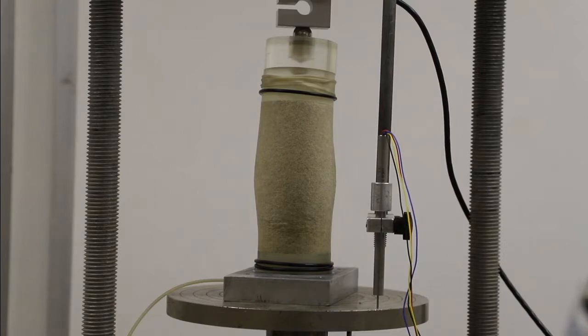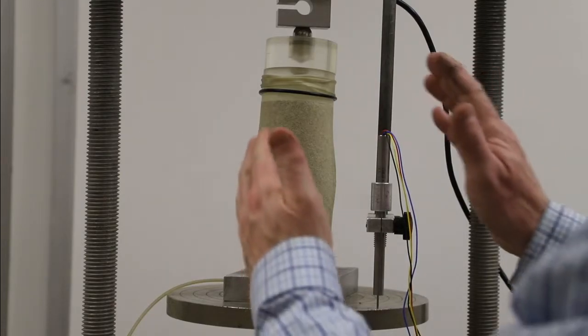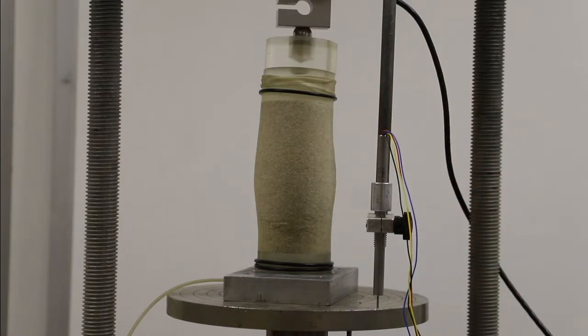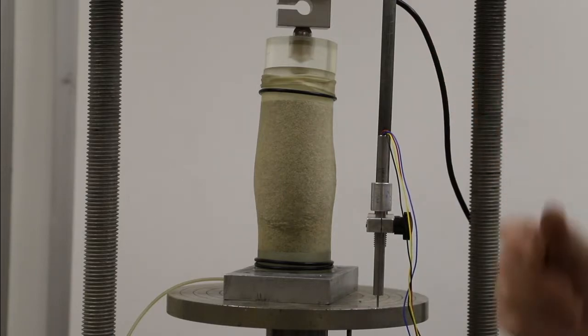And here we are near the end of the loose triaxial test specimen. You can see the bulging is continued. It's not happening at the top and bottom caps because, again, those regions are protected by the caps. We can't have shear planes that go through them because the caps are in the way, and so it's the center portion that deforms more. So any volume changes actually are not really going to be uniformly distributed either, although we assume that is the case.